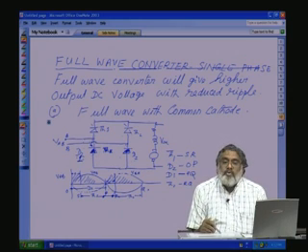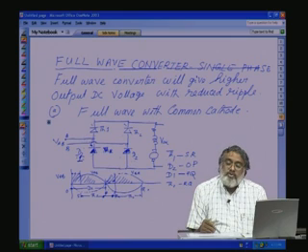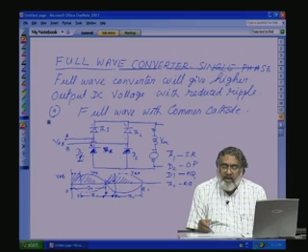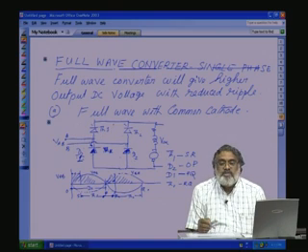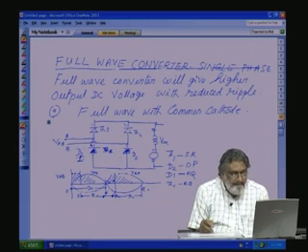Now, to switch off TH1, we have to switch on TH2. The moment TH2 is turned on, B has already become positive and A has become negative. When TH2 is turned on, this positive point comes across the cathode of TH1, and TH1 will be reverse biased and switched off.